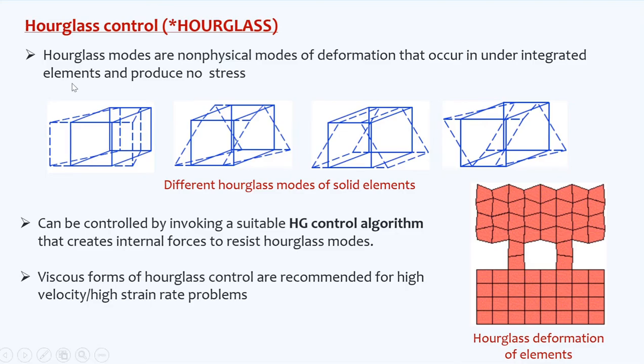You can see here this section is moving and this side is deforming, and here also it is deforming. But at the center you can see the length is the same. Since there is no deformation, it will show zero strain for the total element, and since it is zero strain, it shows zero stress. But actually, the elements of the column are deforming.